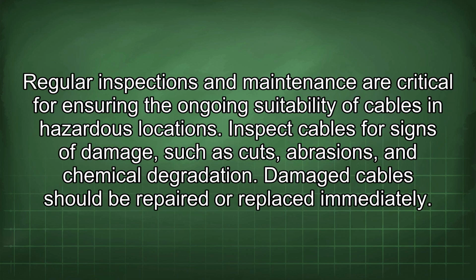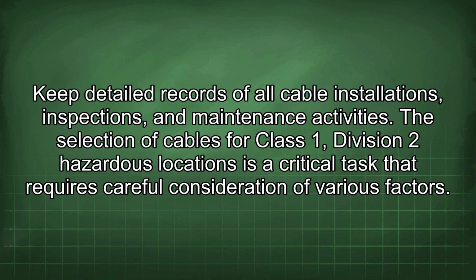Regular inspections and maintenance are critical for ensuring the ongoing suitability of cables in hazardous locations. Inspect cables for signs of damage, such as cuts, abrasions, and chemical degradation. Damaged cables should be repaired or replaced immediately. Keep detailed records of all cable installations, inspections, and maintenance activities.